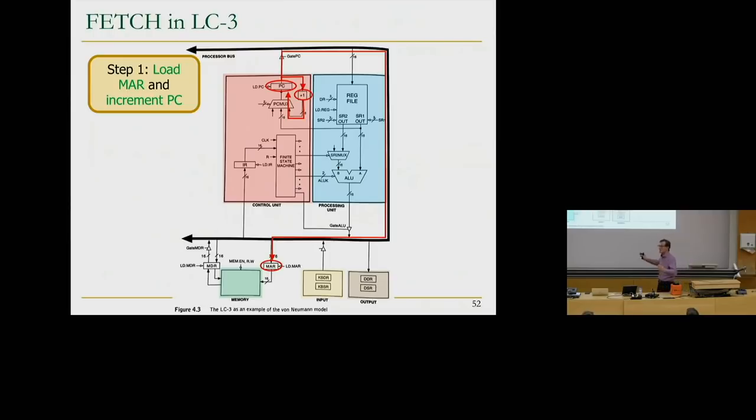So this is our finite state machine. That's the thing that the finite state machine needs to ensure in the first clock cycle if you're fetching. That's the fetch state. So a fetch state will be a particular state in our finite state machine that controls all of the operation. That's the control unit, okay? So what this did, the PC got captured in the memory address register. That's good. In the next cycle, memory access starts.